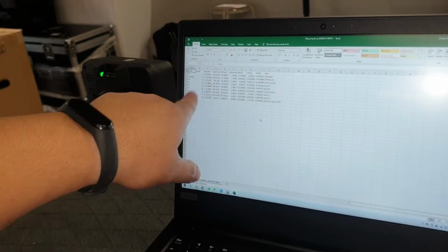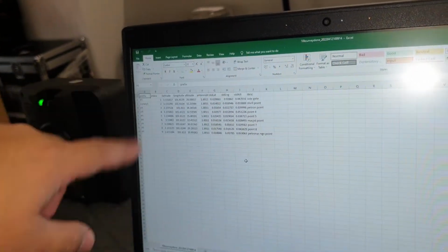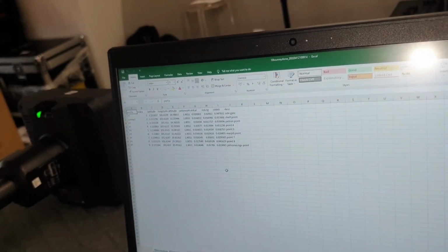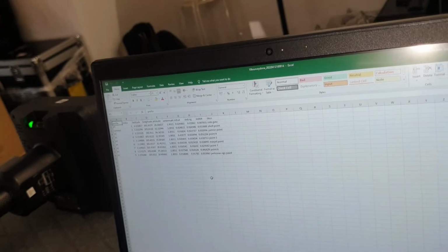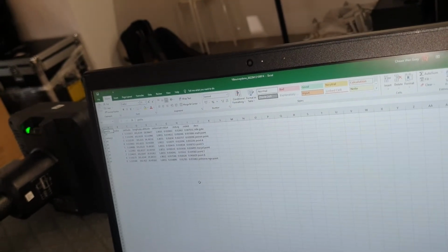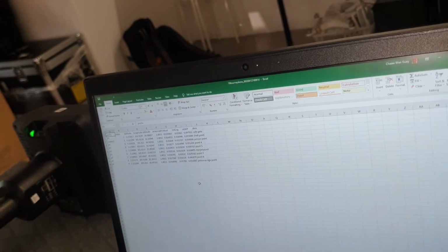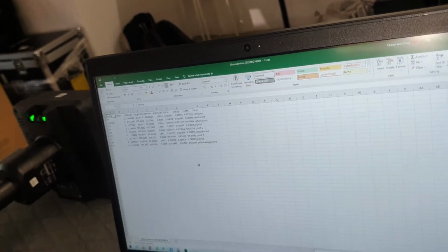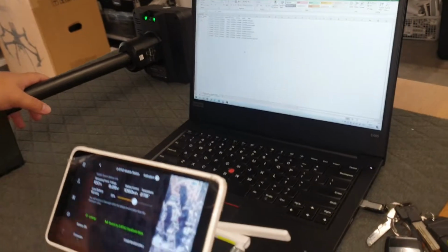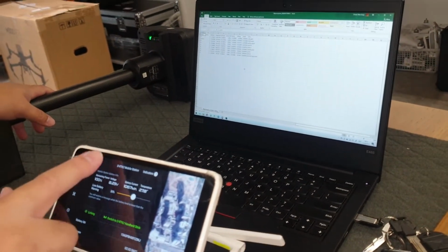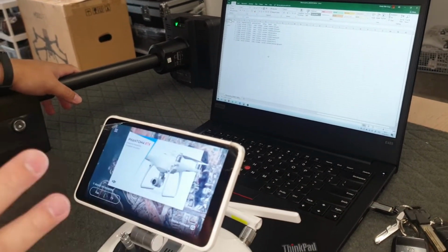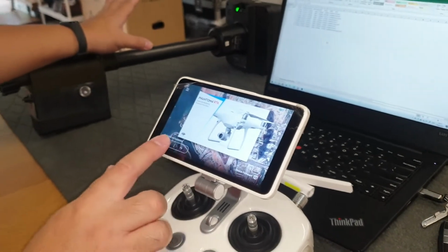That means with all these points, at a height of 100 meters, flying that 2D with that diagonal line, we got 6 centimeter 3D error. Wow, that's lovely. Without tagging any ground control. Right? So yeah, we're pretty confident with this workflow in that sense.